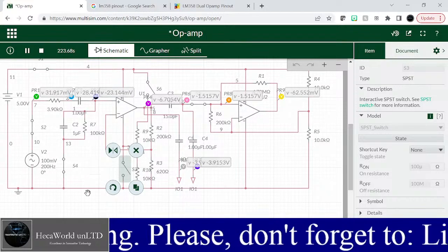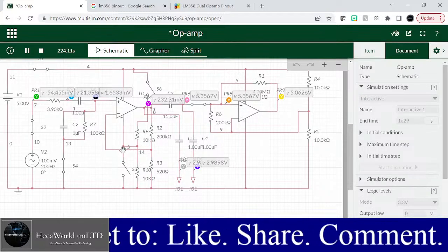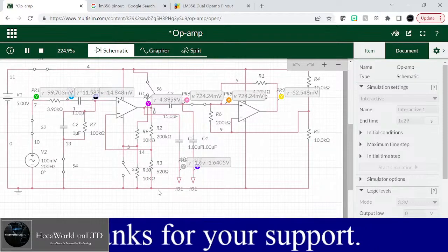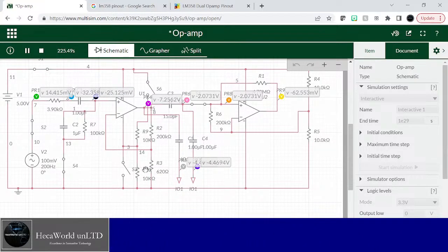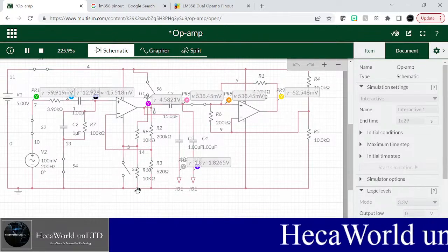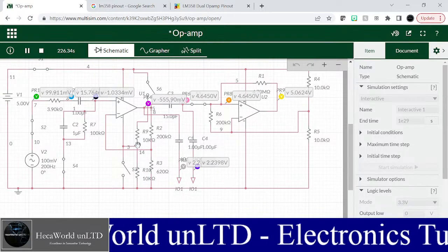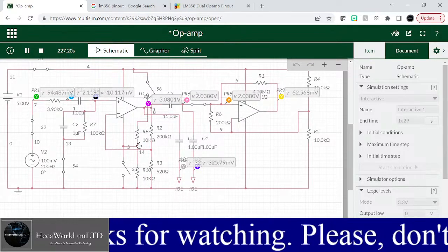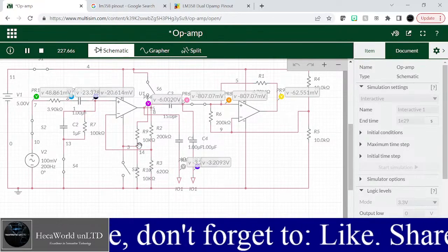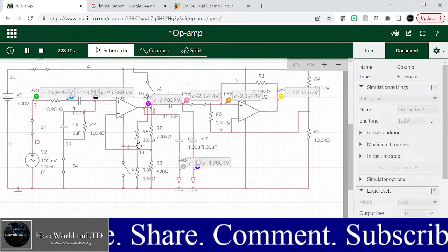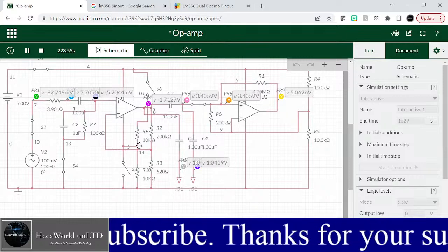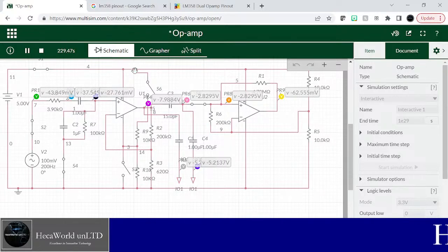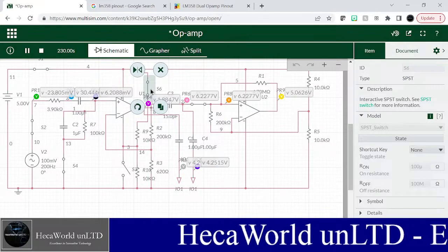And then after we turned it off, pin 4 is now connected in the middle of two 10K resistors connected as a voltage divider. One resistor's pin is connected to ground, and the other end is connected to the power supply. So the center of the resistors is connected together, and then to pin 4 of the LM358. So we're going to close that switch.